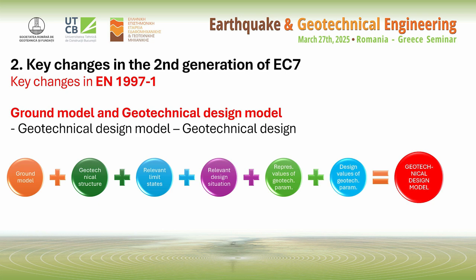After having this ground model, we will add the geotechnical structure that we want to design. We will put further the relevant limit states and the relevant design situations, and we will have to determine, as geotechnical designer, the representative values that are adequate for the limit states that we are analyzing. And with this, now that we have the representative values of the ground parameters, we will determine the design values by applying the partial coefficients for ground parameters. And all this information will compose the final geotechnical design model.